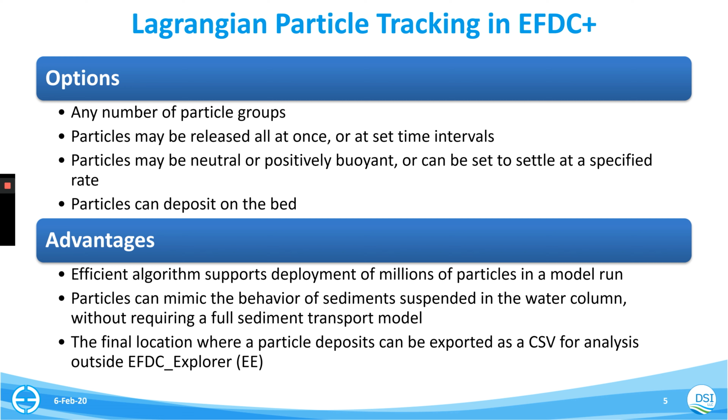And of course, when the particles settle to the bed, you can set up the model so that as soon as they touch the bed, those particles will deposit and they'll no longer be tracked by the model. That saves on computational burden, and it's also a little bit more realistic because particles can't be resuspended from the bed. That's one of the big differences between the results you might get from a model looking at the behavior of Lagrangian particles versus a full sediment transport model.